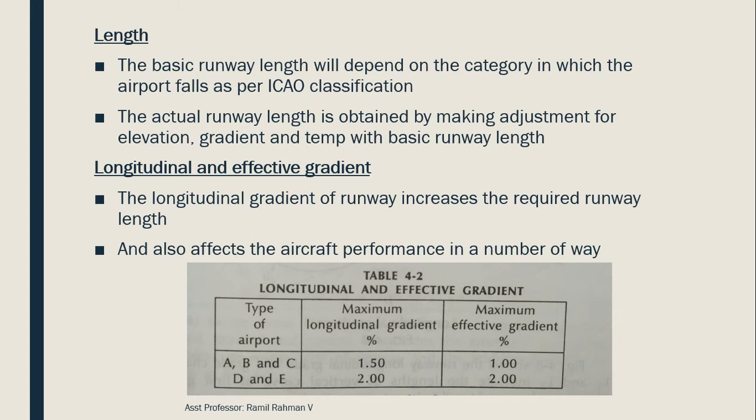Longitudinal and effective gradient. The longitudinal gradient of a runway increases the required runway length and also affects the aircraft performance in a number of ways. This is the table representing the longitudinal and effective gradient, in which the type of airport is mentioned and the maximum longitudinal gradient that can be provided and the maximum effective gradient.